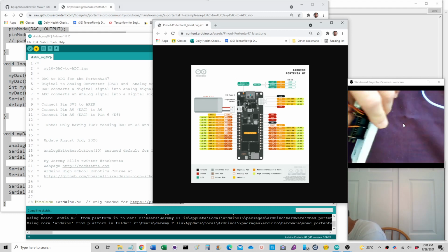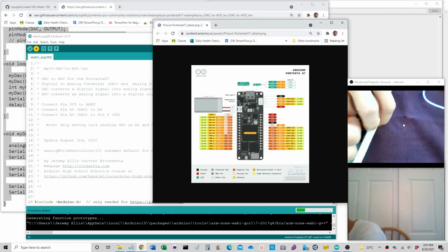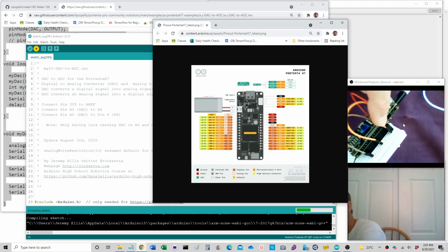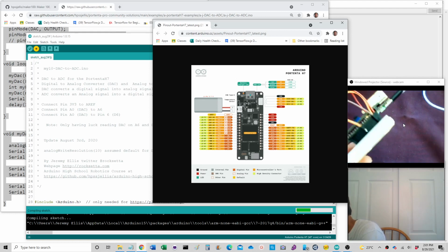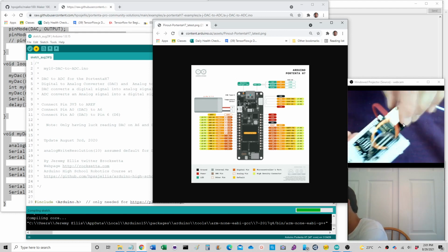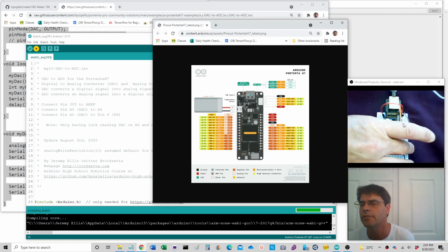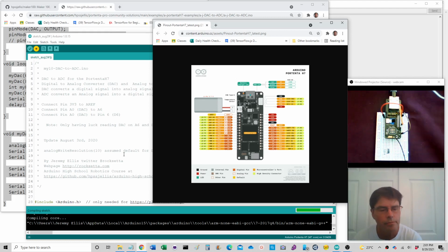And this one is plugged into the wrong one. It's supposed to be A0, which is number 2. There we go. So the orange one's from A0 to A6. The brown one's from A0 to D6, the last pin on the board. Reminder, everything's flipped upside down just to make your life miserable.